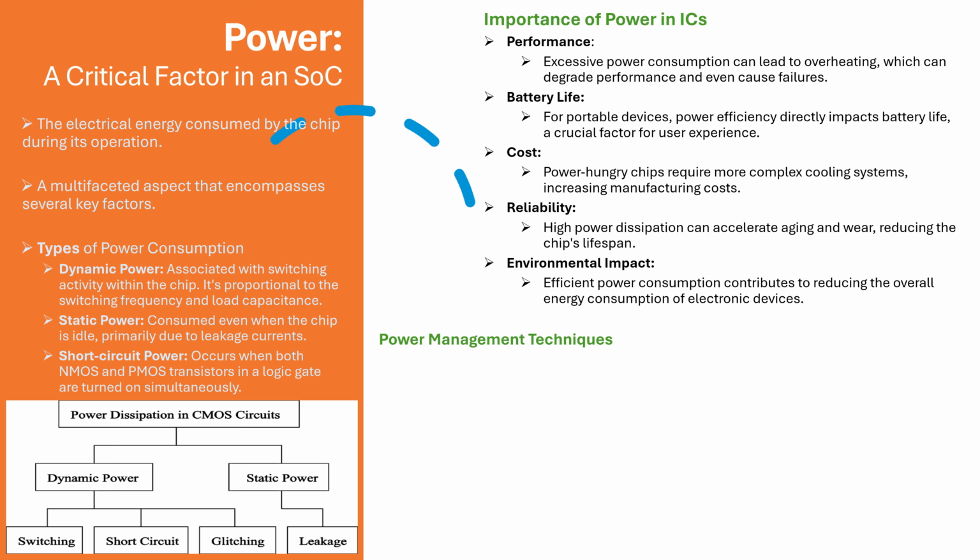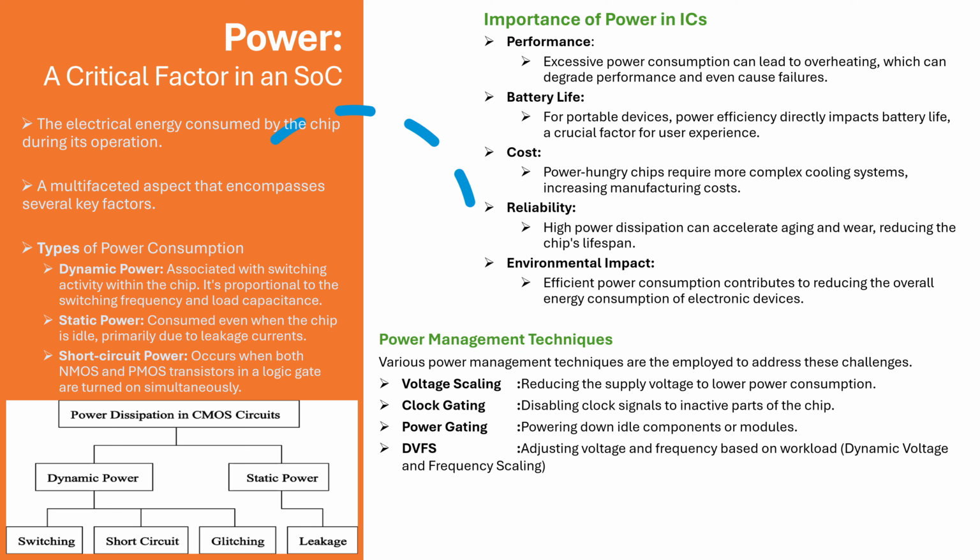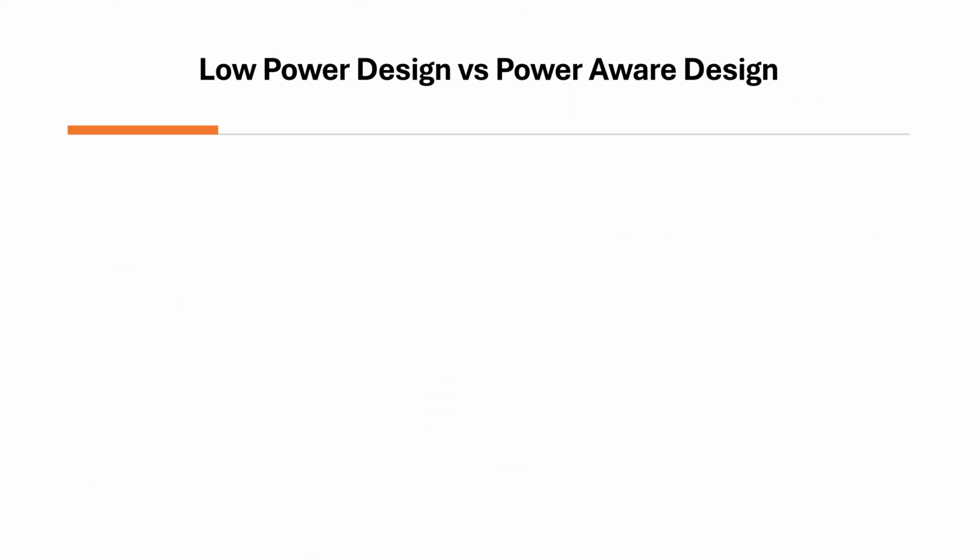Let's list some power management techniques. There are a couple of power management techniques that are employed to address these challenges: voltage scaling, clock gating, power gating, dynamic voltage and frequency scaling. Effective power management is crucial for designing high performance, energy efficient and reliable SOCs.